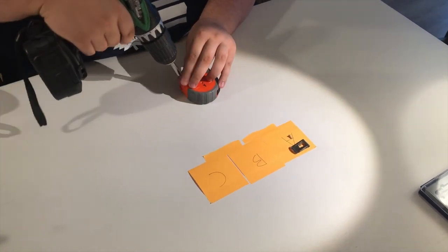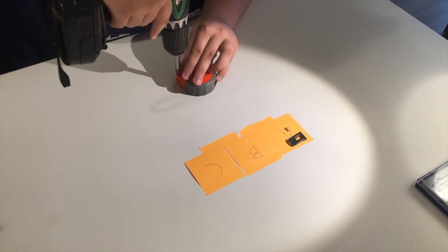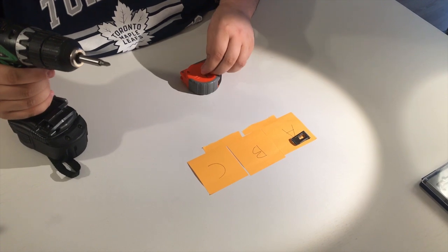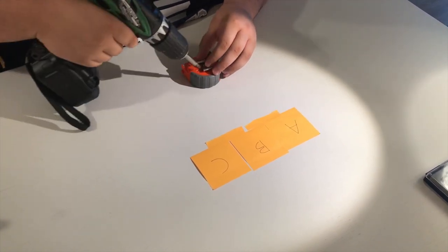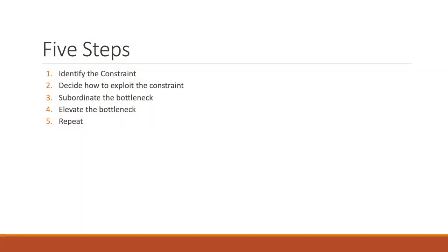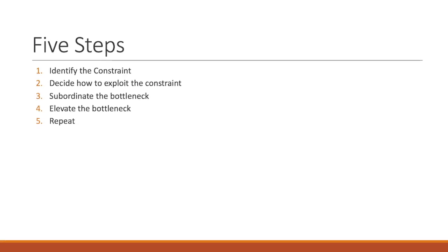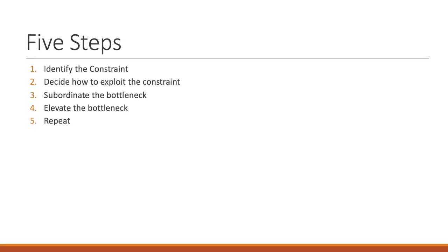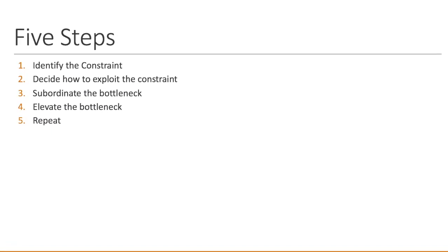We did this by measuring the increased efficiency due to adding an electric drill to replace the manual screwdriver. This ultimately reduced the slack that was in front of the bottleneck and standardized our output. And finally, the last step was to elevate the bottleneck. We did this by training the worker on how to operate the drill. These improvements do require an investment, but ultimately helped increase the efficiency of our assembly line.